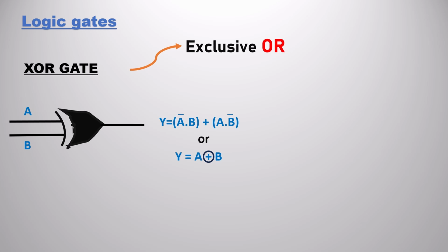In addition to the universal gates, we have two extra gates. These two are very commonly used, so we made them for simplicity. Those two gates are the XOR gate and the XNOR gate. Basically, the XNOR gate is the XOR gate with an added NOT operator. So if we know the XOR gate, it is enough; if you complement it, we can get the XNOR gate.